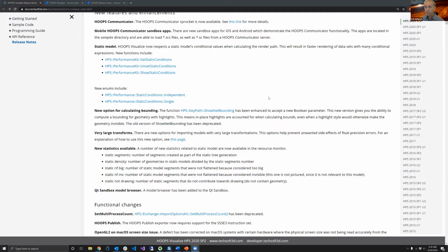And so the model is actually located at its actual construction location versus being located at just the origin in the file. And the problem that we have is the rendering engines are, of course, floats, right? So everything gets boiled down to floats in order to get piped through to the drivers, and we suffer from precision problems, and it causes camera issues and Z fighting and all sorts of bad behavior.